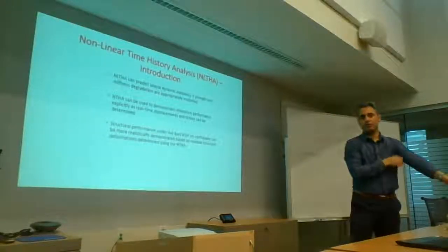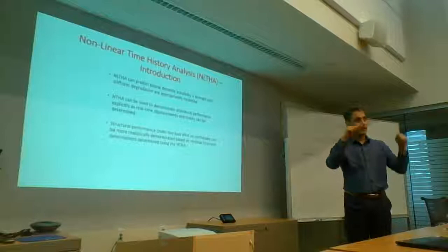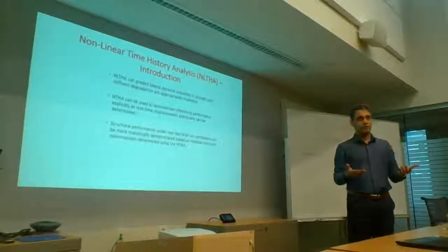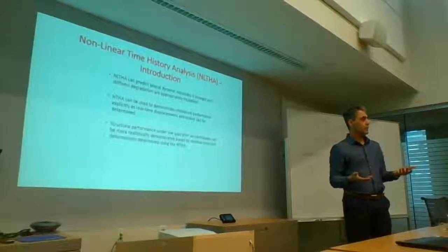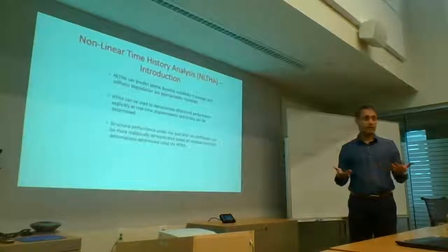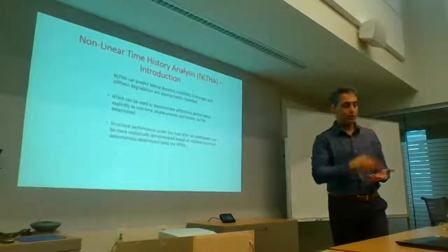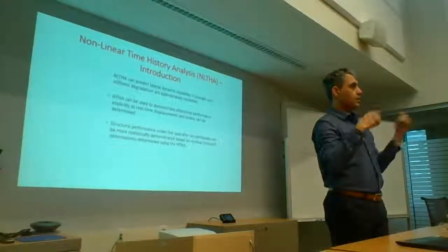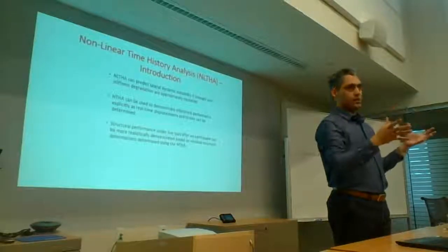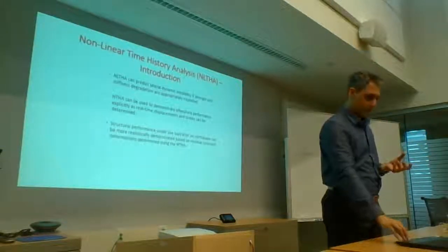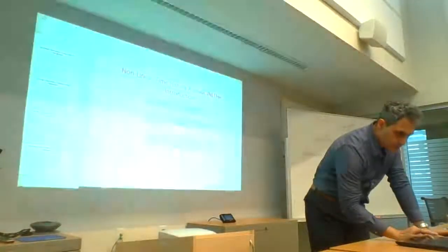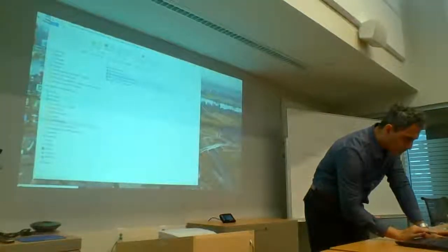And if you run a nonlinear analysis starting from that stress state, then you're able to see if you will be able to put the live load on it or not. As we were talking about before the break, the only way to do it otherwise is really to fudge it with just a pushover analysis, and I elaborated on that a little bit. Okay, so moving on.